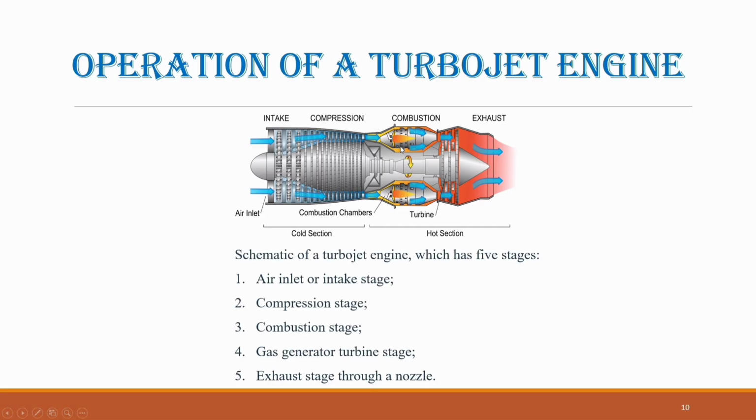The heated airflow leaving the combustor carries substantial energy into the turbine. 4. Gas generator turbine stage. The gas generator turbine extracts energy from the hot exhaust gases to drive the compressor and maintain the engine cycle. This stage rotates faster than the compressor, adding significant kinetic energy to the airflow. As air is compressed, both its pressure and temperature increase, creating extremely hot gases that must be carefully managed to avoid damaging the turbine blades.